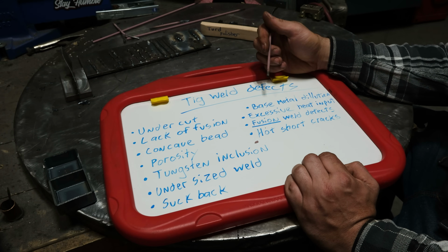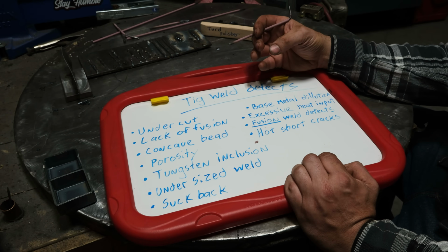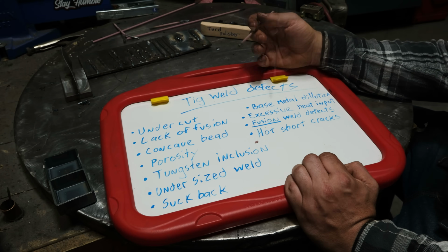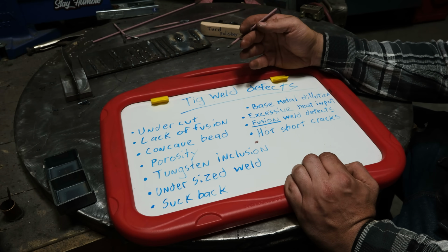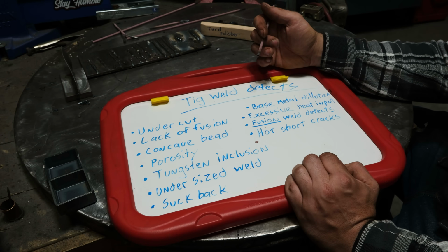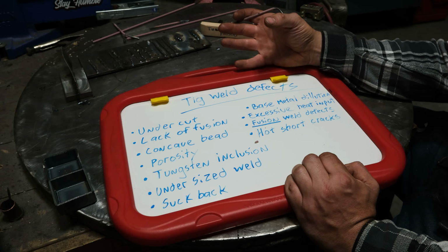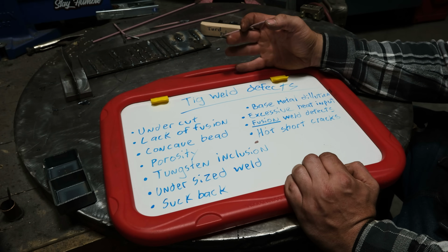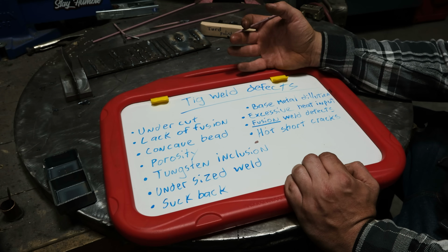Like if you go and TIG weld chromoly tubing or steel like AR500 or any number of tool steels, or even aluminum for that matter, or another good one would be cast iron or spring steel like a leaf spring. If you just try and fusion weld those, or you don't use enough filler, you will produce an extremely brittle weld due to partial carbon absorption. It will absorb carbon from that material and then become brittle, but there's a lot of other things at play with other tool steels besides just carbon. And long story short, your weld is going to be junk.